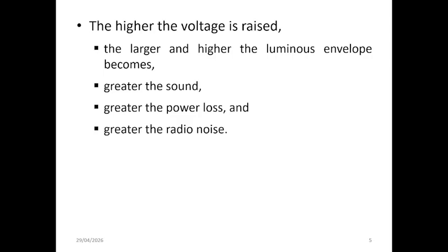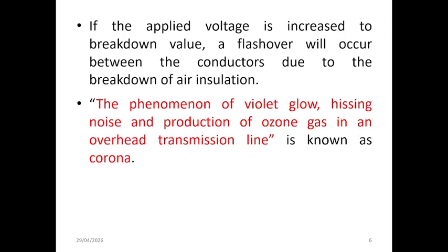In addition, radio interference becomes more severe, creating greater noise that can distort nearby communication and broadcasting systems. Therefore, higher operating voltages require more careful conductor design to control corona effects.